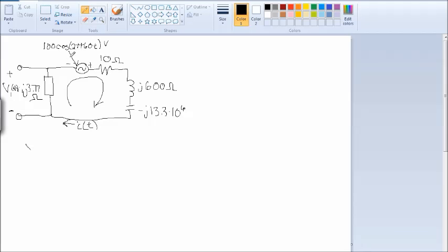Oh, before I get into that, here's another thing. As you can see, we're going to end up dividing a bunch of numbers in complex form with j's in them, the imaginary number, and real parts. And we're going to have a cosine in there. It's not very fun math to do that. So the easiest way, what we want to do is convert all of the numbers into one similar format. So you can either convert them into polar form or rectangular form.